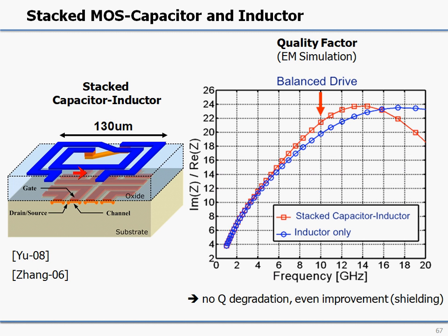As mentioned already before, in better low noise or high performance, and thus low noise applications, we need to use an inductor in the oscillator. So we might as well try to make the best of it and reuse the area under the inductor. In this example, what was done is to create a capacitor under the inductor that we can then use in the loop filter. So this is a MOS capacitor.